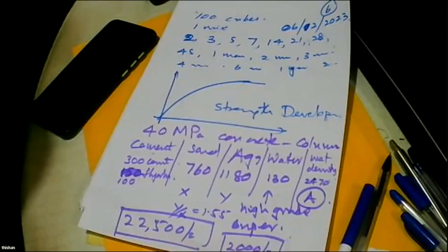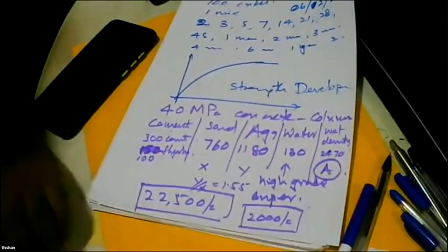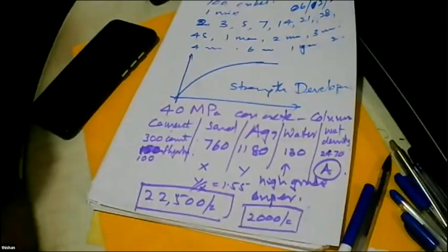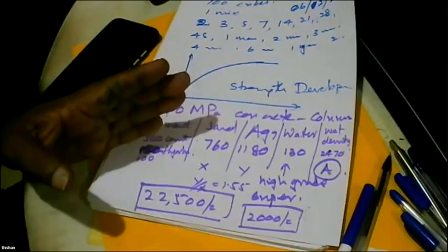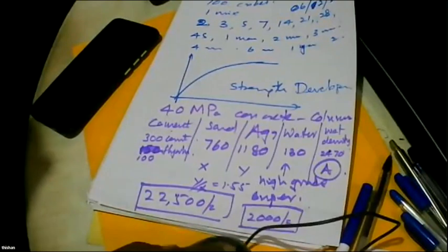Any other question? Yes, then engineer Sajeev Kant asks, for mix proportion calculations, which strength to use, cube strength or cylinder strength? No, I'm using cube strength, no, cylinder strength, because the moment you know the cylinder strength, you know the cube strength, because this table is available.